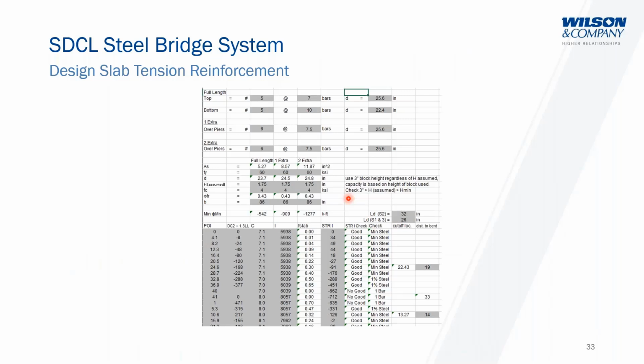And to reiterate, the whole reason for the block itself, the compression block, when you're sizing that, you want to make sure that you size it so that it's not too small and that it wants to fail prior to your deck steel.